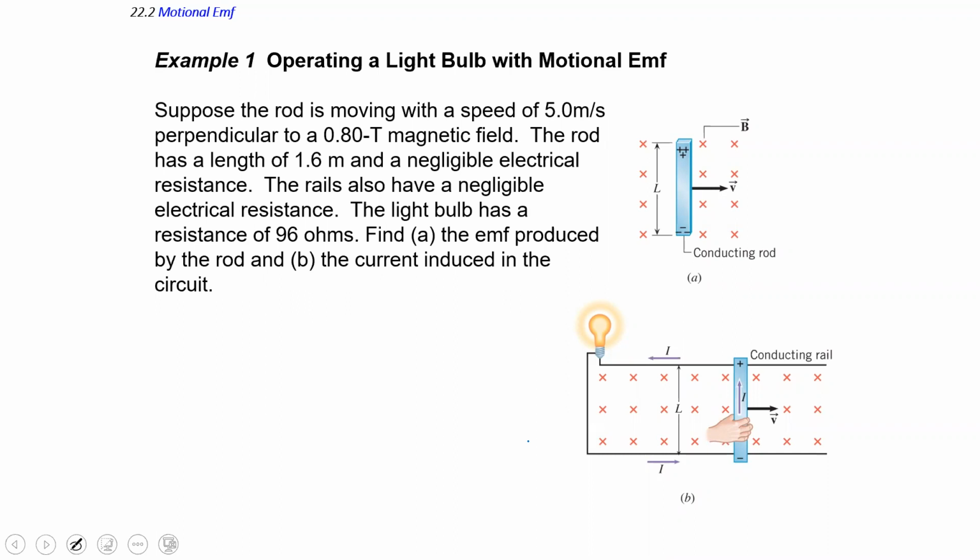So we can put in a light bulb and ask what is the current that flows due to this EMF through the circuit. When we apply Ohm's law here, the resistor acts as a limiter to the current flowing. This is not a coil producing current independently, freely. It's a coil producing current, and that current goes and is used somewhere. So you can't go back and say, oh, the current should be this value and it's too big. There's a difference between a loaded coil and an unloaded coil, which means a coil with a resistor and a coil that's just connected up. So it's always find the voltage, find the EMF, and then use it in the circumstance that's appropriate.